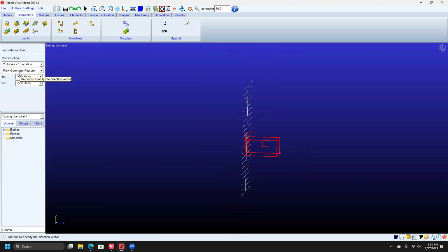And then I will want to select the rigid body. So it's going to say part 2 is going to pop up like that. And I'm going to click on part 2 as our first one. And then ground, you'll see that pop up and you'll click ground as your second one. Okay, so then we'll want to select our location, and we will make our location the center of mass,